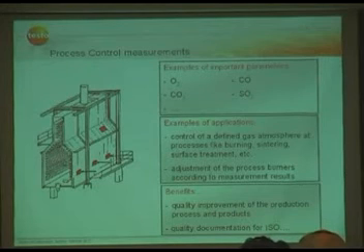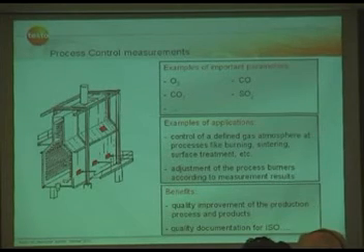And this is very easy with our instruments because we have a different range of sensors, or we have additionally a dilution system. If you have a higher concentration in your application, the instrument will switch on the dilution automatically, which means a dilution is like a measurement range extension. But I will show you this later on.